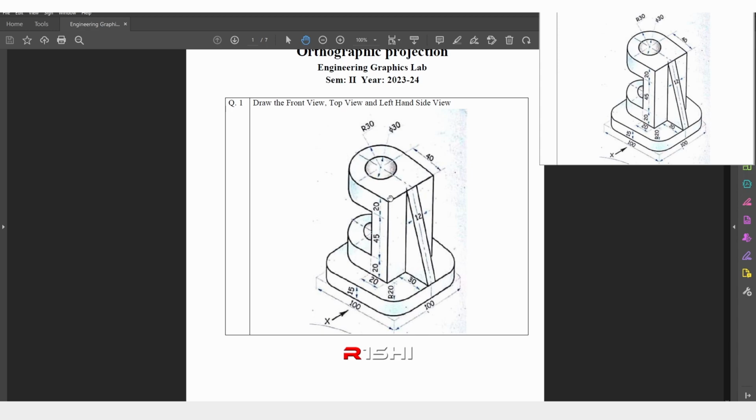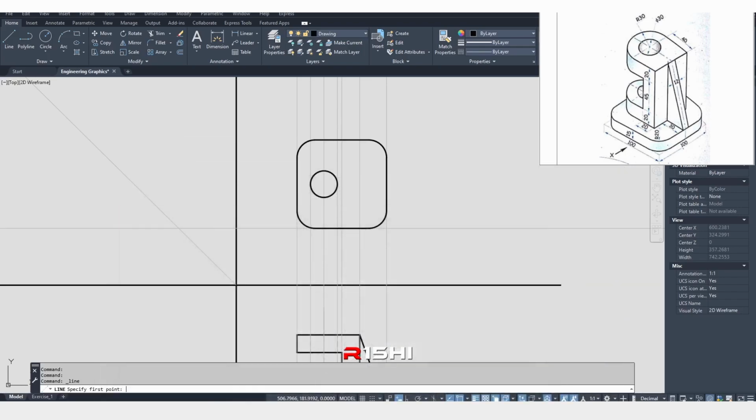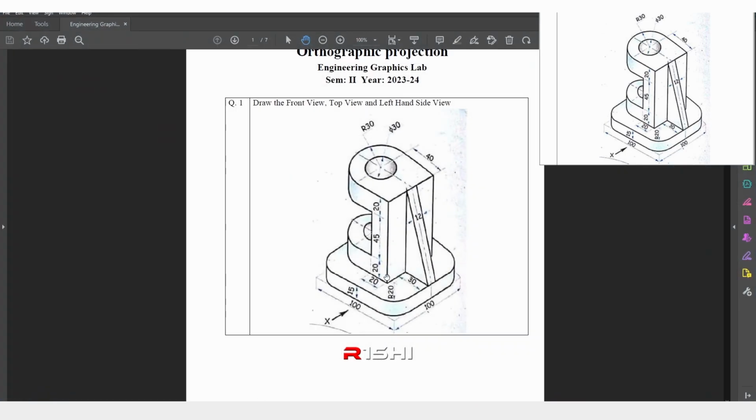So we want to pinpoint this point of the line, okay, or this edge. Okay, we are going to locate this using our coordinate system in AutoCAD. So how? Okay, you can see that the diameter of this arc is 60 because the radius is 30, right? So the length of this edge is 60, but obviously the length of this edge is 100.